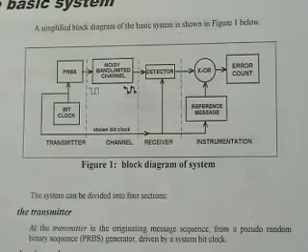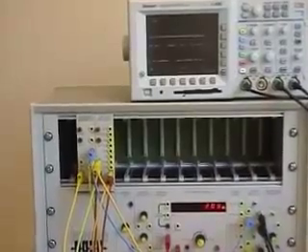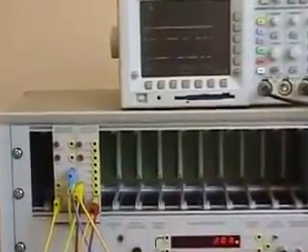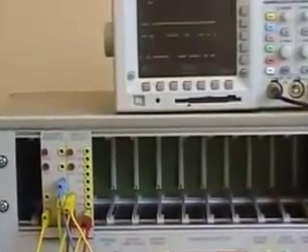The receiver front end uses a detector block to regenerate the distorted received signal, and then a bit error rate instrumentation section using an exclusive OR function to compare the received signal with a known local copy of the transmitted sequence. We commence by patching together the transmitter section. TIMS allows us to model any transmitter, channel or receiver, either individually or as complete systems.